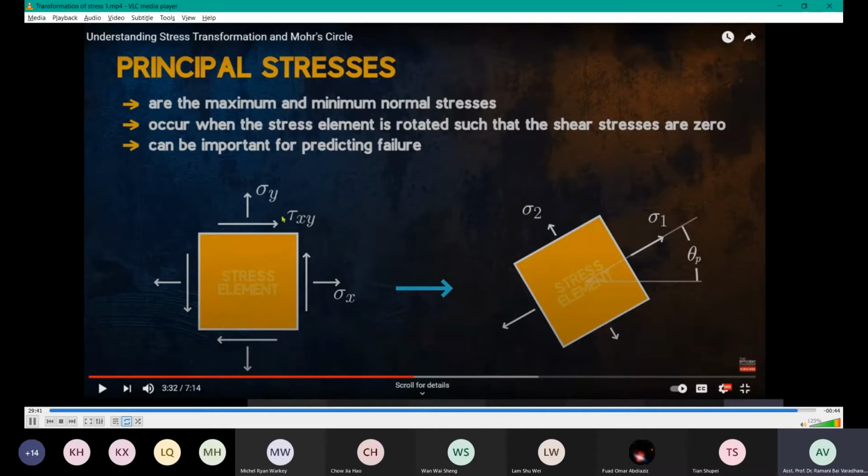You understand? So this is showing just a normal distribution of the stresses in the normal direction and on the plane, right? The shear and normal are shown as usual. You calculated this in chapters 1, 2, 3. This is the value you are calculating, right? And then when it is rotated or in motion, you will have changes in value, reaching a maxima or minima. These are the things governing any design or helpful for predicting failure. That is why we have to undergo this study and learn how to draw Mohr's circle to find these unknowns, minima and maxima. Maybe you can see this video later.